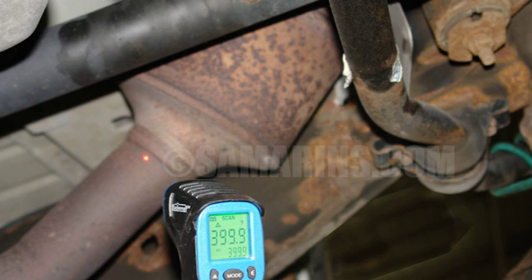There are several possible causes of the P0420 code, including a faulty catalytic converter, an oxygen sensor that is not working properly, an exhaust leak, or a problem with the engine's air-fuel mixture. The most common symptom of the P0420 code is a check engine light. Other symptoms may include reduced fuel economy, poor engine performance, and a strong smell of exhaust.